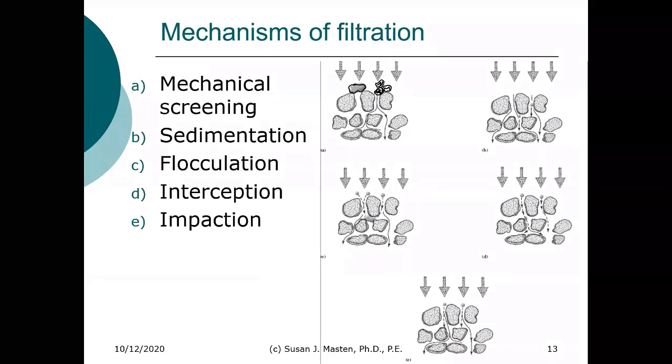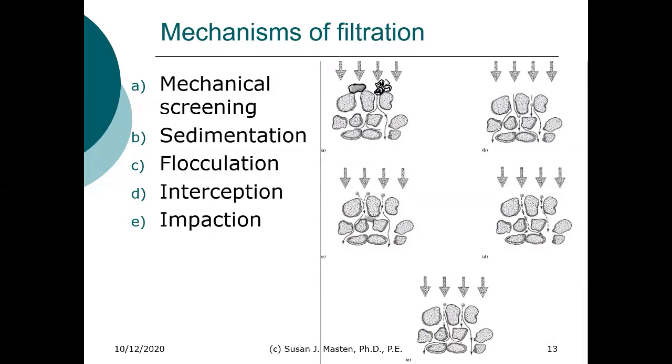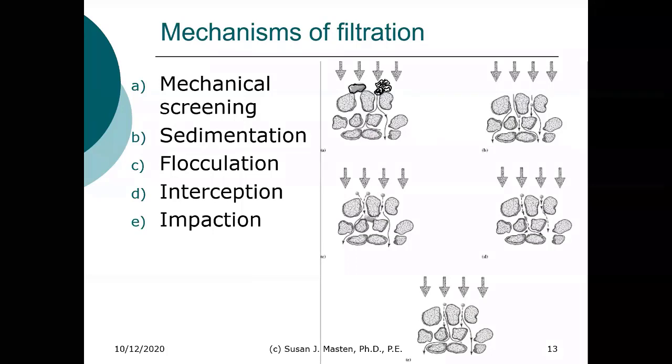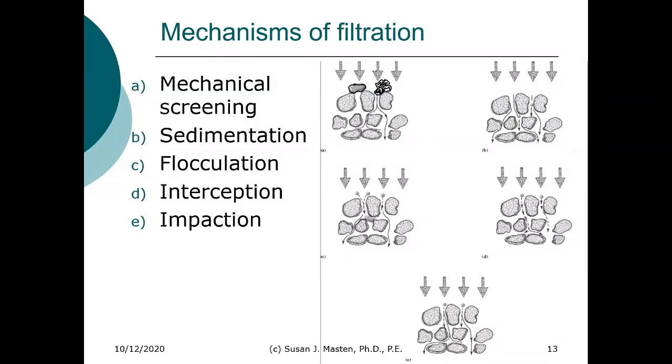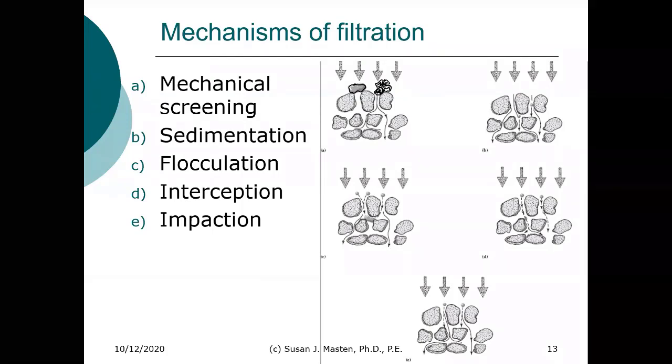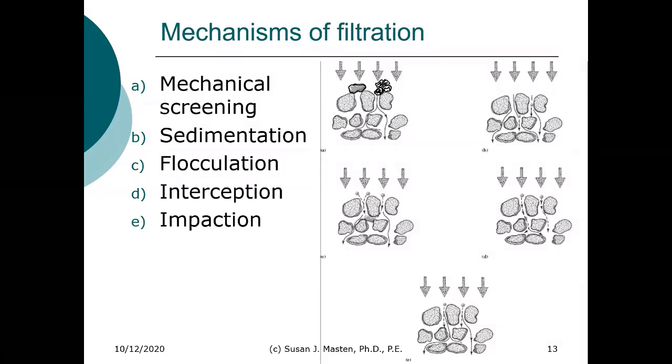Same thing happens when we talk about these mud balls. So if you get enough of these together here, then you form this kind of clump of material that is difficult to remove. We also talk about sedimentation. Here, the mass of the particle and the diameter of the particles are large enough that the particle actually settles. So this is moving by settling, and it deposits on a particle. So you can see it's smaller than the pore space, but it deposits on that particle and it's removed by settling.